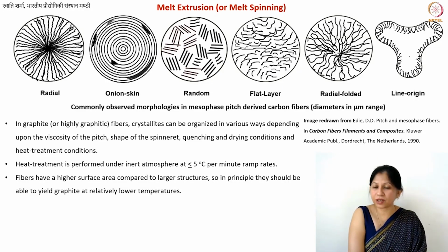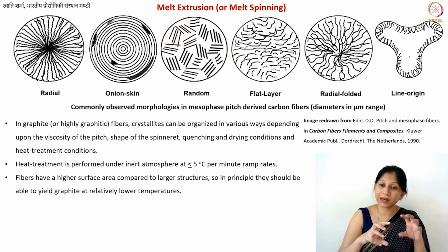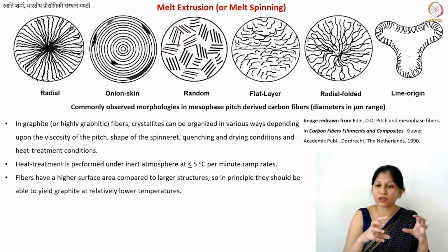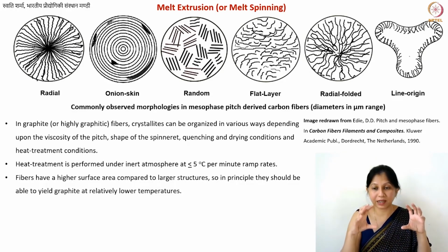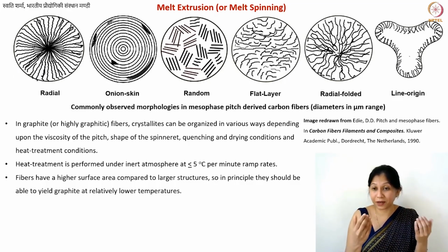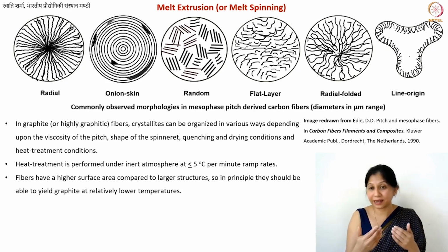In the case of fibers, you need to understand whether or not high Young's modulus is important. If you are using these materials for making certain structures, for manufacturing purposes, often you need high stiffness, but not all the time. Let's say if you're making biomedical implants, what you may need is a little bit of flexibility, so that when tissue is growing on top of, let's say, a bone implant, the tissue is able to press it a little bit. That is why you may not need very high crystallinity. But that depends on your application.